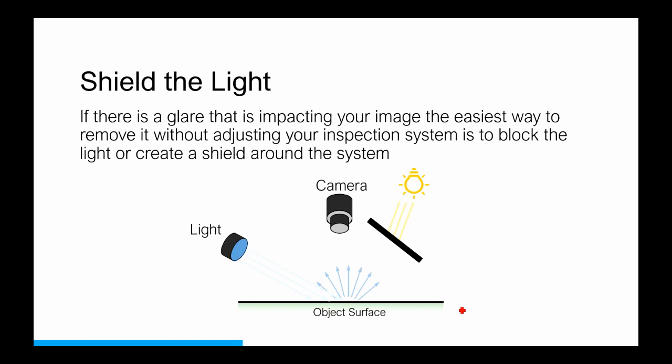In the scenario I talked about where there was light reflecting off of the machine, the way that they handled that was they found a matte material that they put over the reflective parts in their machine. So instead of it being a shiny chrome, they put like a matte black paper around it. So that black absorbed the light, diffused the light, didn't have such a strong reflection, and it was removed from their vision system altogether.